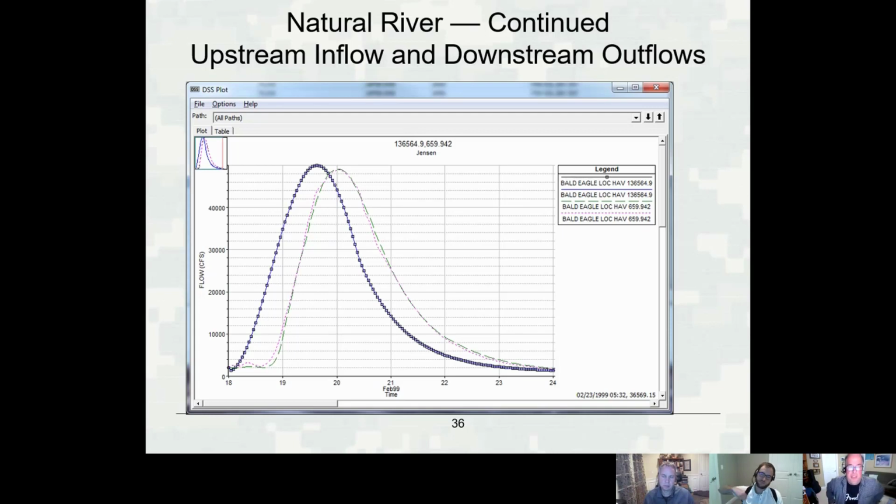Whereas with the finite difference, because its solution is based just on change in water surface, cross sections real close together might not have very much change in water surface at all. So it has no trouble handling that. That's one thing the finite difference method can do better than the finite volume: have cross sections super close together. So one problem is people are going to have models they developed with finite difference, and some locations are going to have cross sections like 2 feet apart. And then they're going to try to run it in 1D finite volume, and it's not going to work. It's going to go unstable at that location unless they use a really small time step. So you're going to have to get used to thinking, I don't need cross sections really close together.